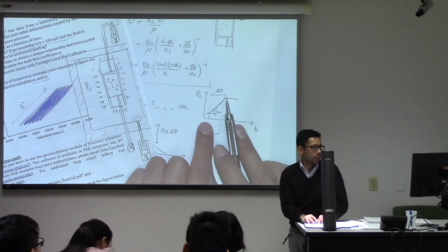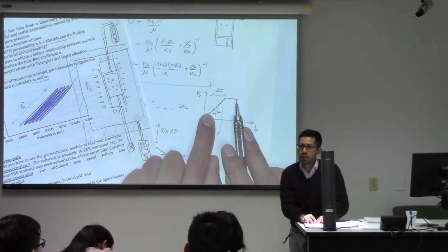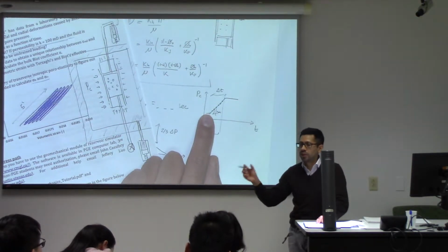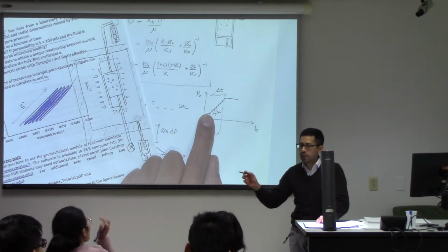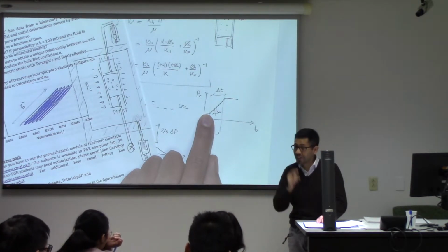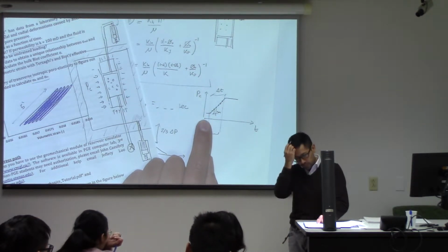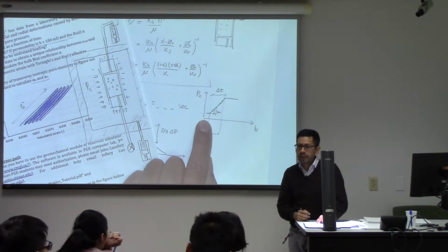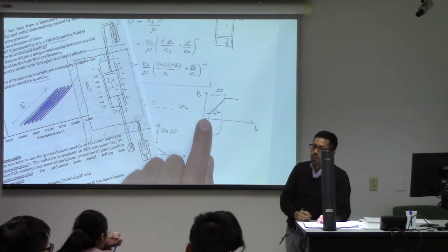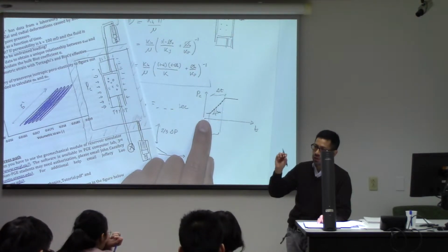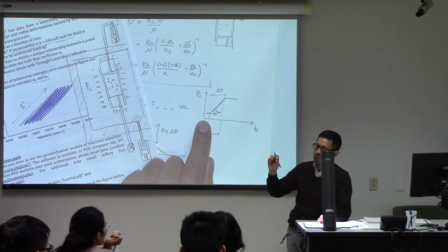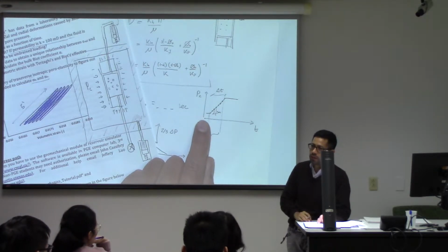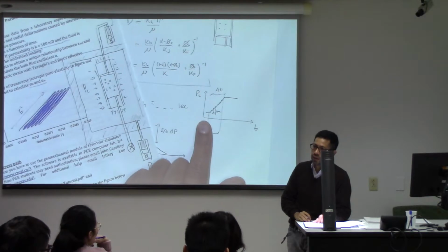Let's take the example that now we do this in 1 year, okay? We're also adding a strain, a very small strain, in 1 second, 2 seconds, 3 seconds, but very clear that's going to be undrained, right? So probably the answer here would come on comparing what is the change of volumetric strain that we're actually doing per unit of time to the pressure change that we would expect.